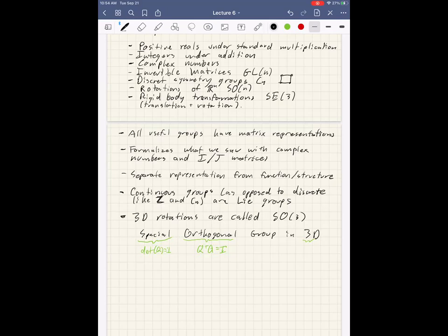Aside, yeah. Another question. Can we generalize the fact that rotations are a group to different attitude representations? Does that imply that the quaternion is also? Yeah, in fact, it's a group representation. It's just another representation of SO3. Quaternions are a little weirder. We're going to get to that probably next time. The whole message here is there are groups, which are things that act a certain way, and there are representations of the group, which are just ways we write them down. So all those attitude representations are just representations of SO3. They're all ways of writing down the same thing, and they should behave the same way in some sense. That makes sense?